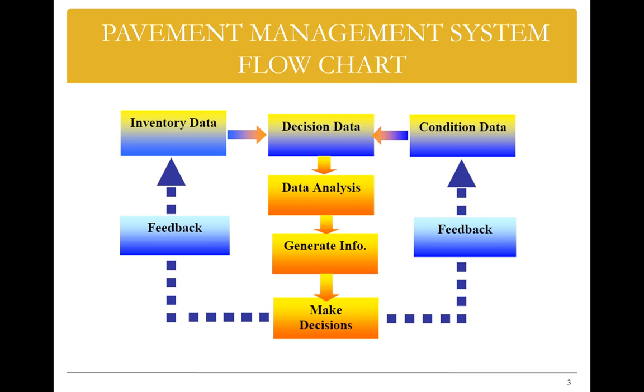So based on the data analysis, now we can generate information, basically in the form of a report. We're going to come up with a report which talks about what data was collected, what analysis was performed, and eventually, and this is what makes the difference between an engineer and others, to make a decision. So now you need to come up with a decision. For example, if you recommend a chip seal for fixing low severity fatigue cracking, then this is the recommendation.